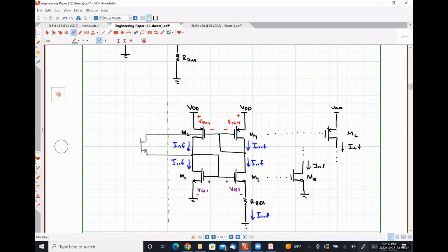So we have a transistor, let's call this MS3, where the S is for startup, where the drain is connected to the gate of transistor M3, and the source is connected to the gate of transistor M1. This guy is just acting as a digital switch. So it's either off or on, no other performance other than that.